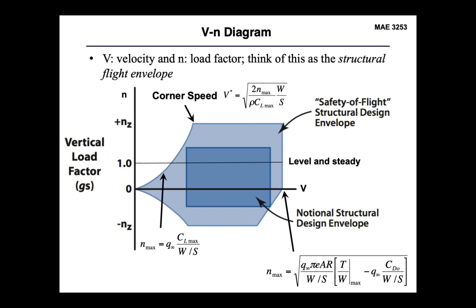And so the maximum value of your vertical component in this is then going to determine what that overall capability is of your aircraft to be able to pull this maneuver. And this is really going to be, again, dictated in two directions, both by the specifications of your aircraft, how maneuverable do you want it to be, and then your structural design capabilities. What did you design it to be able to structurally withstand with any given maneuver?